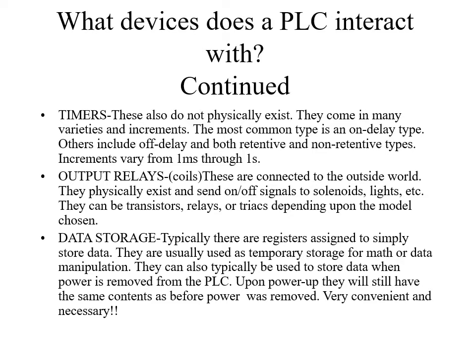And then we have data storage. Typically, there are registers assigned to simply store data. They are usually used as temporary storage for math or data manipulation. They can also typically be used to store data when power is removed from the PLC. Upon power up, they will still have the same contents as before power was removed. Very convenient and also necessary, since power interruption can happen unexpectedly.